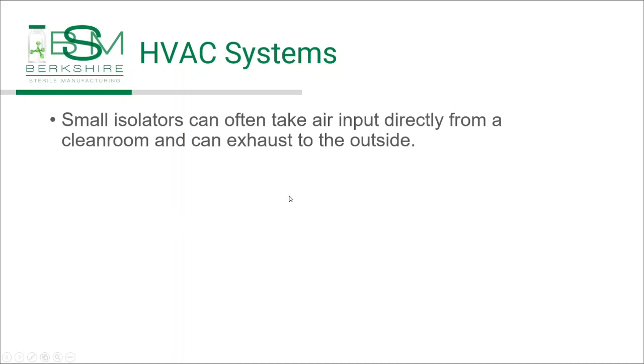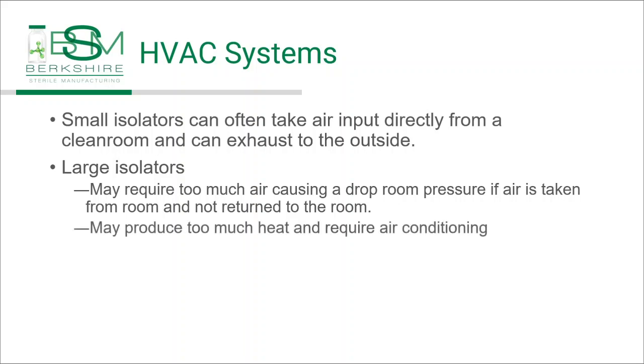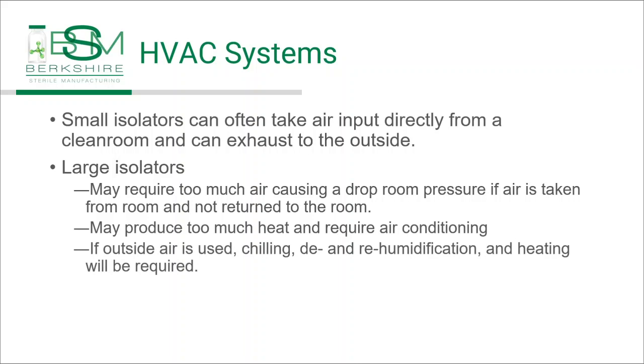Okay, small isolators can often take air directly from a clean room and can exhaust to the outside. That's the isolator that I just showed you. Large isolators, however, may require too much air, which would cause a drop in the room pressure if the air is taken from the room and it's not returned to the room. Also, large isolators, because they have large fans in them, can produce too much heat and require air conditioning. If outside air is used, chilling, rehumidification and heating will be required.